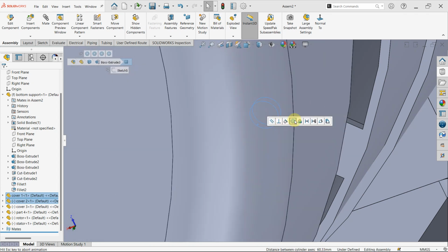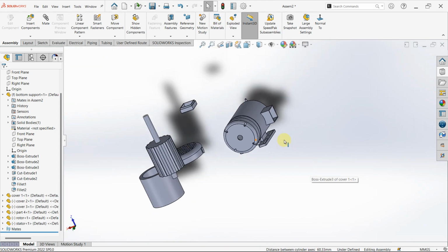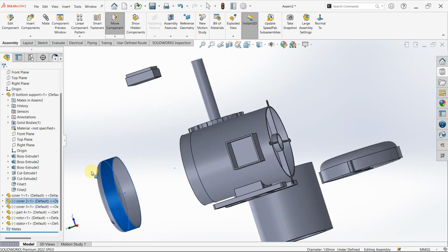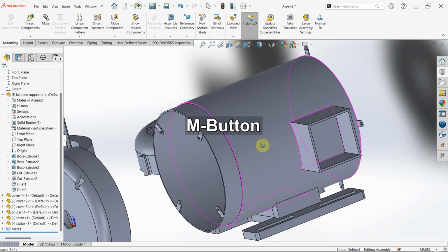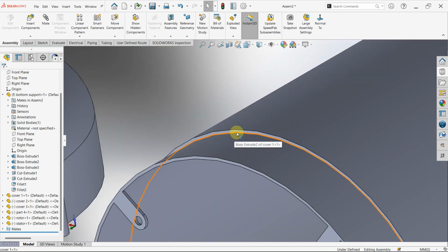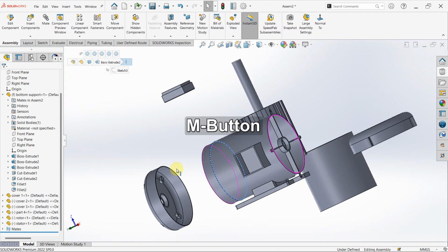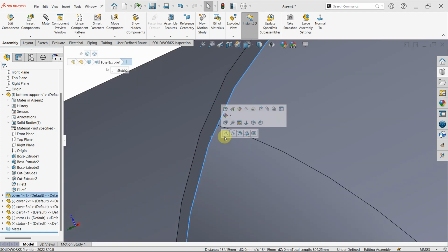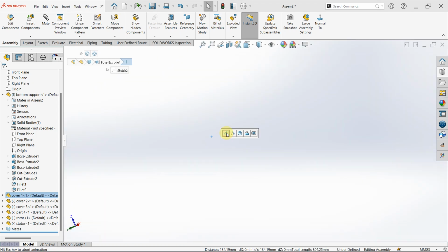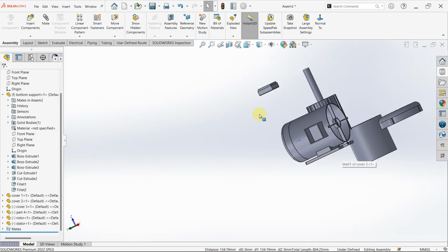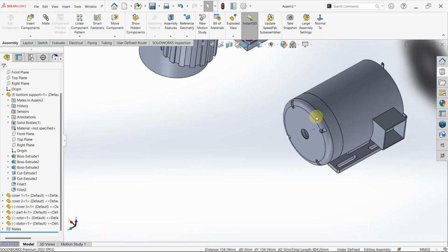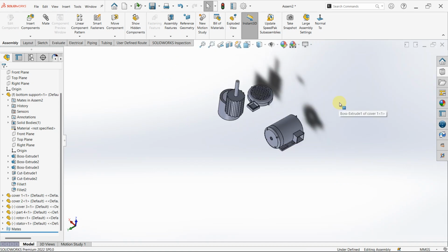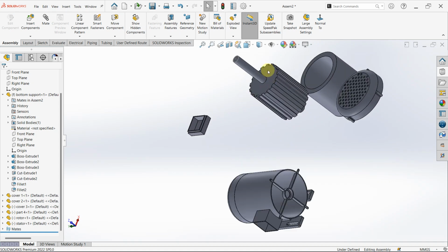Okay. So now good. We have the right orientation. You see it can go forward. So I can now add the coincidence relationship again here. So it's now positioned, isn't it? There's no degree of freedom again. So it's fully fixed.